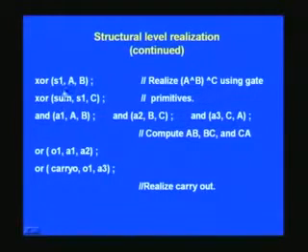And finally you plug this into the next exclusive OR along with the third signal which you have not used earlier to get the final sum output here. And similarly you can AND A·B, B·C, C·A, and OR this A1 and A2 here, right, assign it to an intermediate signal here, and once again you can use this and continue ORing with this A3 which we have not used earlier. So thus we have got carry out as well as sum here.